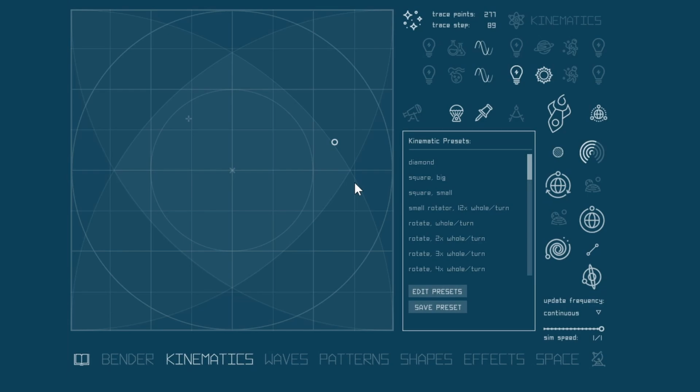Then the icon here is azimuth toggle. Click on it to move azimuth by 45 degrees relative to 0 point. It reacts to key modifiers, so hold Ctrl to move by 15 degrees, Alt key to move by 18 degrees or Shift to move by 1 degree. Use it with Snap to Grid and you can create different basic geometric shapes.